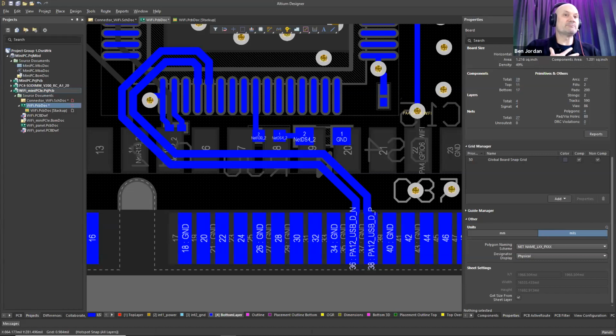However, how I would personally do it is I would route them all on the schematic first using the number suffix, and then I would use the list panel, which you can open with Shift F12, and find all the net labels that have that same bus name. Let's say it's the P bus.